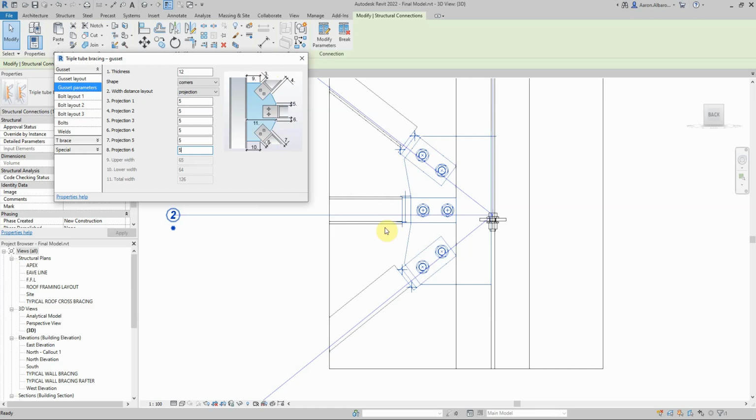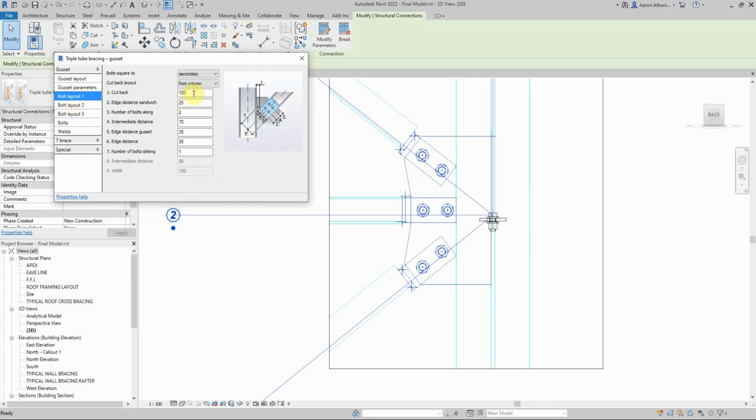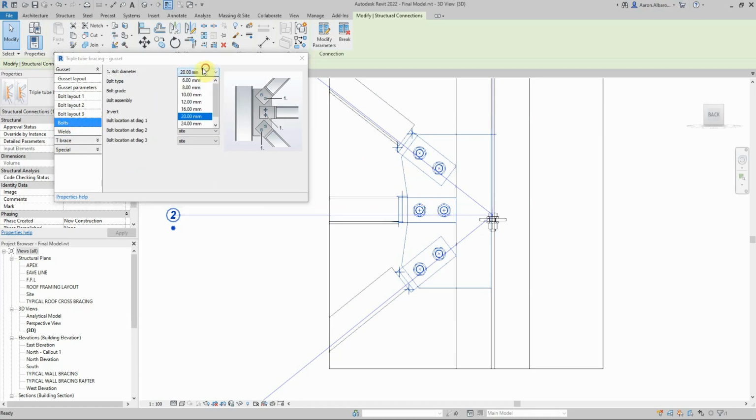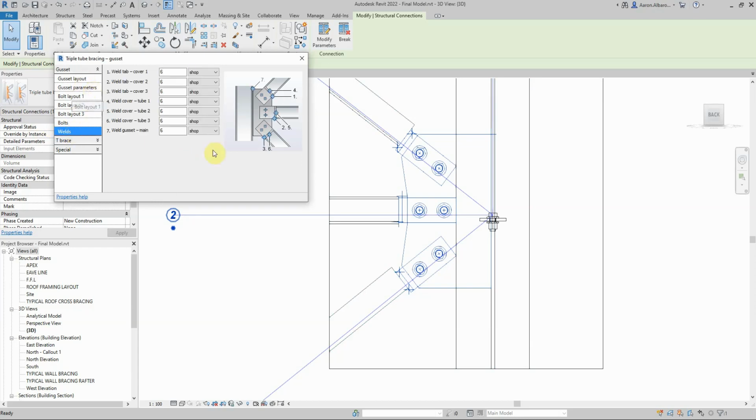You see it obviously. And what else? So we've got that edge distance. Again, let's keep all minimum edge distances at 35 millimeters for all of them. It's important for us to do that. And I think we are done. The bolts, 20 millimeter structural bolts, and those snug type with 2 washers, and that's it. We're good to go. So that will be our connection.